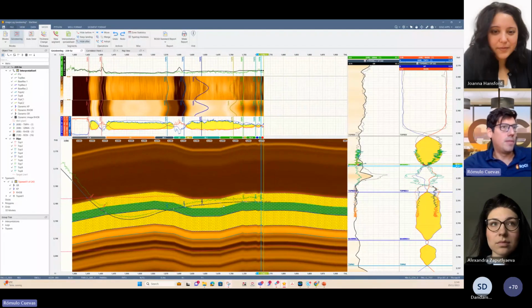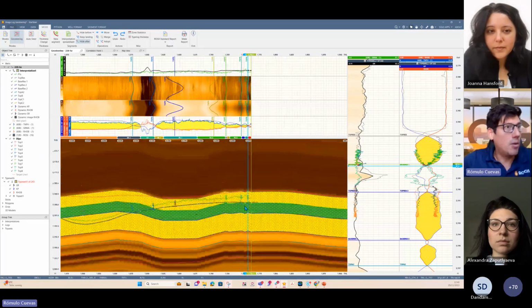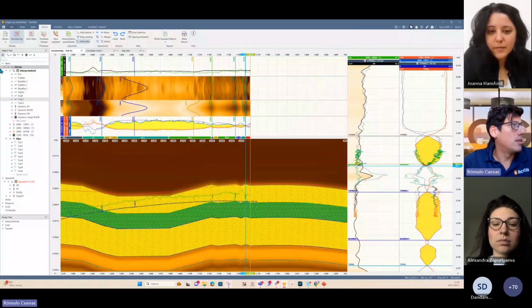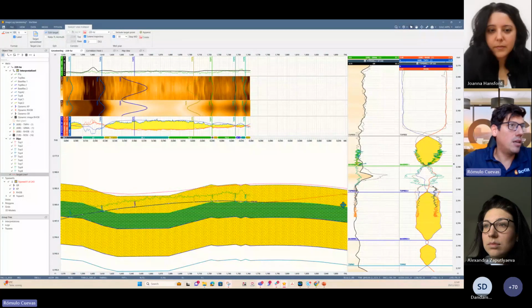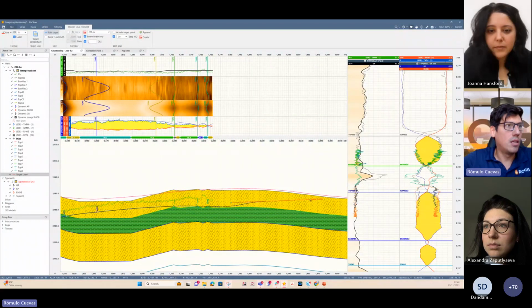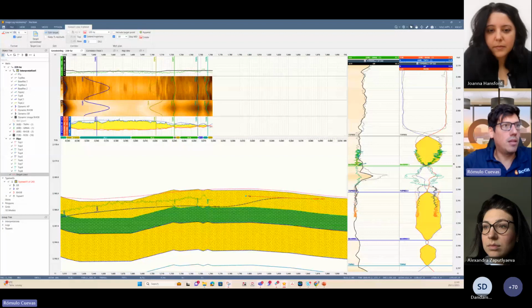Okay, now I can add the last piece of data, or I can show you, for instance, how to project again. So now we know we are near to the base, so I can come back here to my target line. Okay, I can edit the target line. I can take this target line and move it upwards here. Now I know I'm really close to the base, so I need to actually build inclination to place my well inside of the upper part of the reservoir, like this.